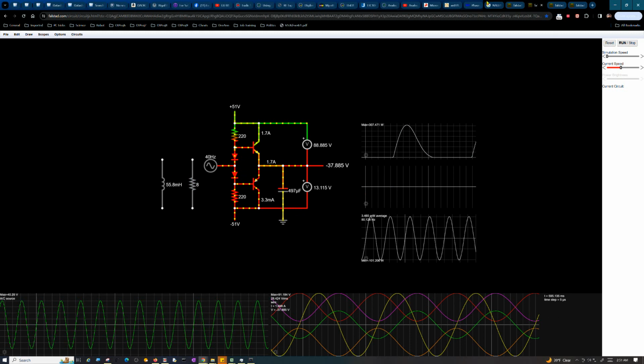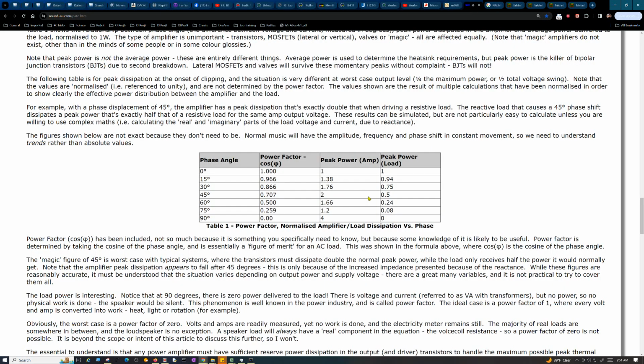And just like they talk about in this article, it has a lot to do with the safe operating area. They say that average power is not what kills a bipolar transistor. It's peak power that does it, because it actually generates a little hot spot. For example, if this square rectangle here were the die of a large power transistor, because of that peak power it may develop a little hot spot like right here.